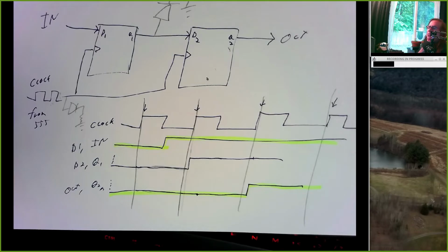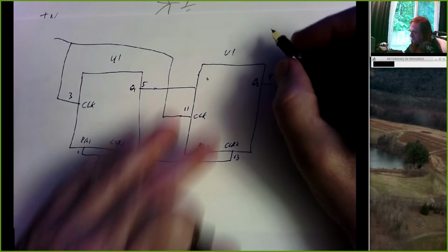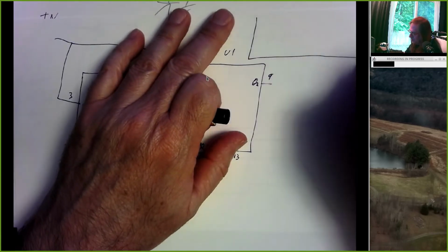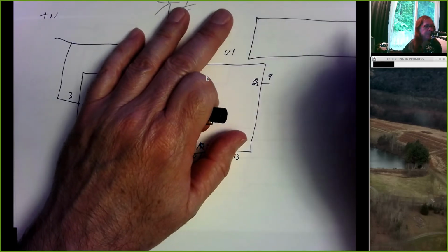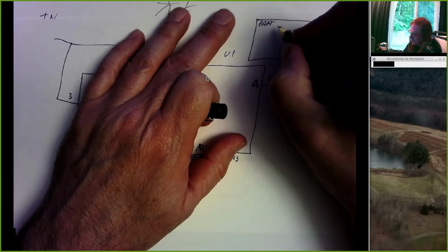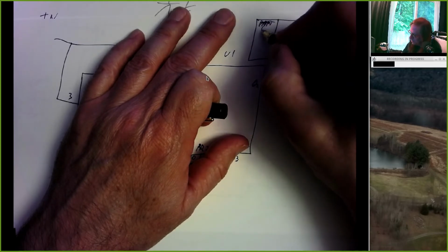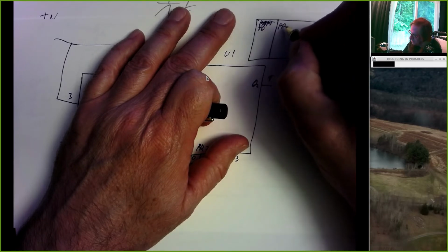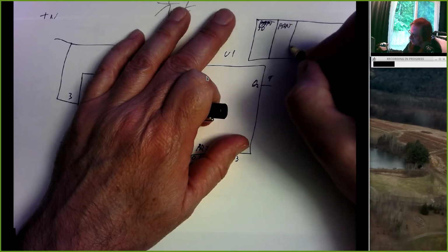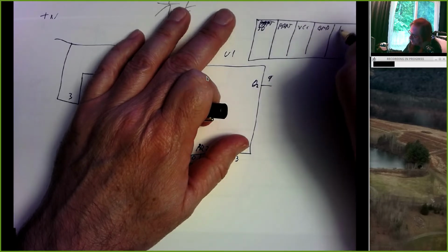Alright, let me go back through some questions. How much info should we show in our key? If by key you mean the component ID block, that's usually something like ID, and then what's the part, and where does power go, where does ground go, and which pins are not connected.